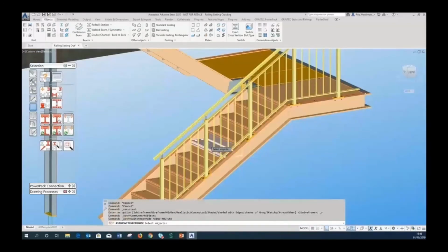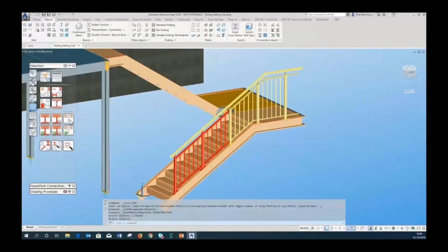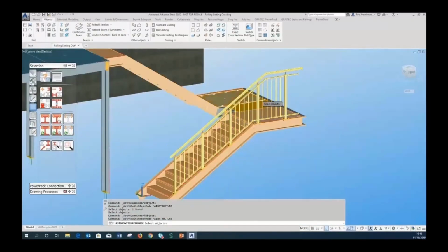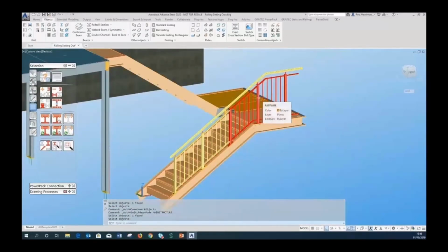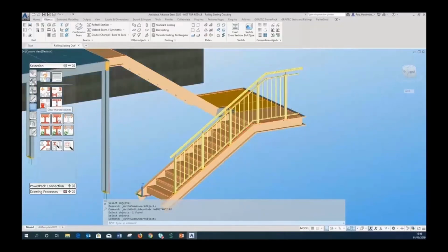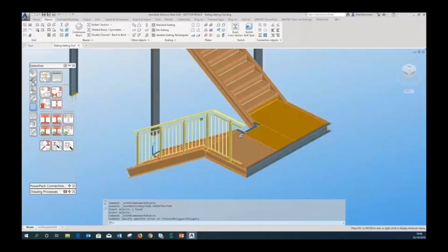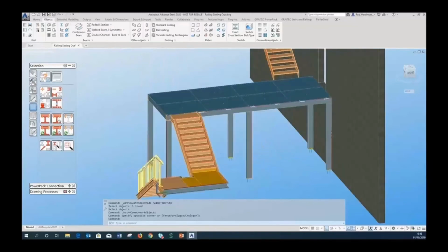It's realistic. Check the assemblies. And now you can see that the bottom portion is one assembly and the top portion is a separate assembly. So I now have 3 separate assemblies instead of one big assembly. I haven't exploded the macro, I've just adjusted the welds. So it's a really nice, easy, quick way to divide up your railing conveniently.